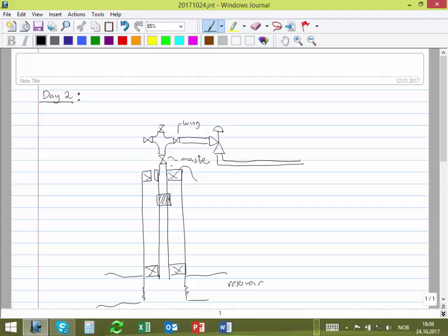Okay. Later, if we have time, we talk a bit about architecture. But you have to put here a piece of pipe that will bring the hydraulic fluids, at high pressure, that will have to keep it open. And this part here is what we call the tubing hanger. Did you hear about the tubing hanger before? No? Okay. It's the part that is making the seal first between the casing and the tubing, and it's also supporting all the weight of the tubing. The tubing is actually hanged on this piece, and this piece is transferring the load to the casing. Yes, and we'll see how it looks, if we have time.